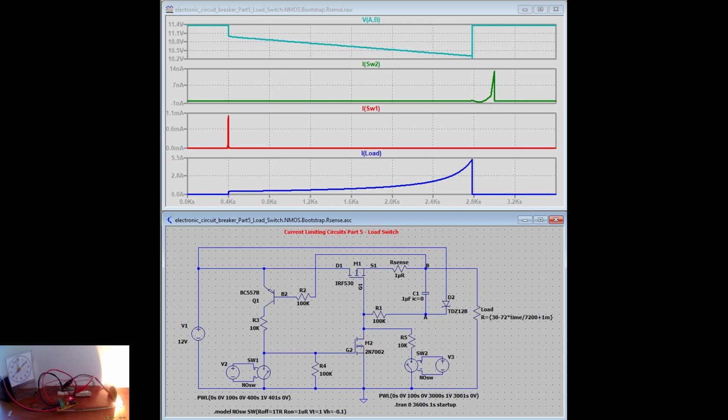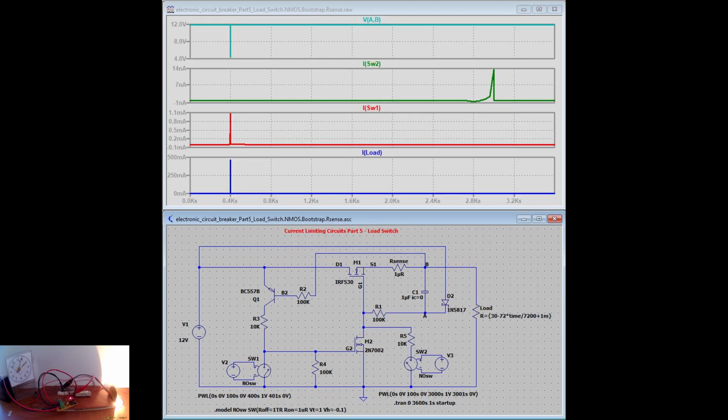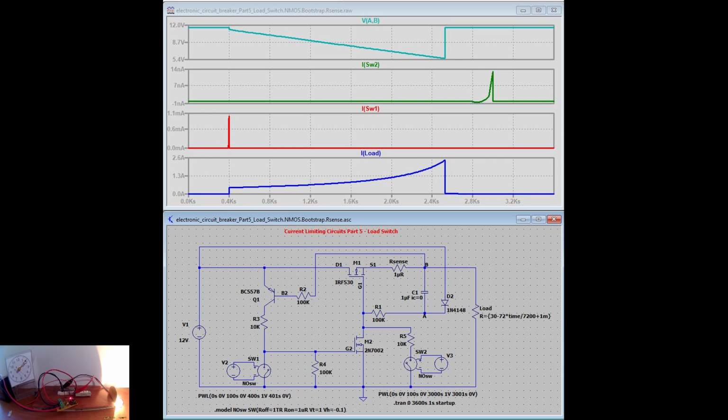For a high current, high voltage power supply, in the final circuit, a 12 volts Zener diode was used. During the breadboard tests I used a Schottky diode 1N5817, which did not work. There is no reason for a regular 1N4148 diode not to work.